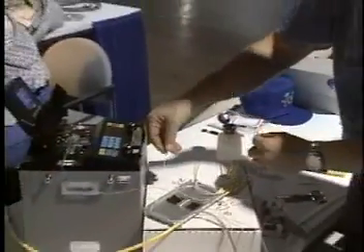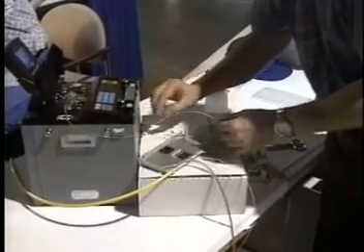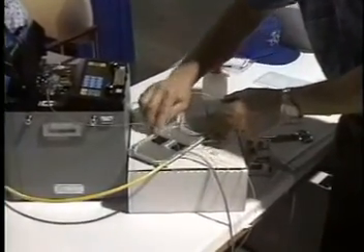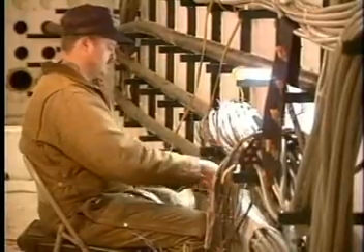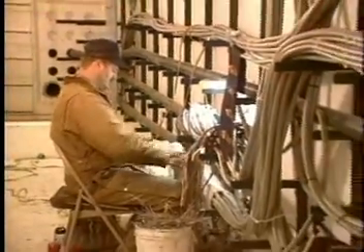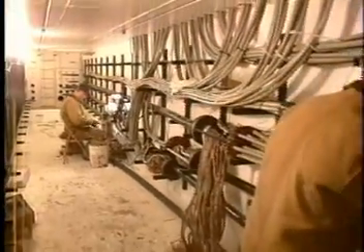The continuing development of optical fiber has resulted in fiber cable with extremely low transmission losses compared with the best copper conductors. Such low losses make it possible to construct transmission systems with tens or even hundreds of kilometers between repeater sites, as opposed to 700 meters for coax cable TV trunks. In addition, losses in copper cables increase with frequency, so the more information you try to force through a copper conductor, the higher the losses.